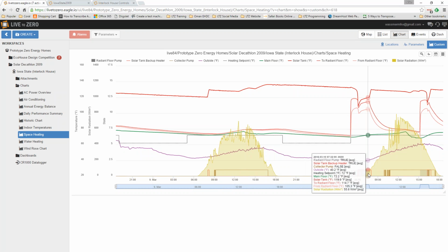So the backup heating element was on for about, I think it was, 2 hours, 6:06 through, okay, 2 hours. So 5 kilowatts continuous for 2 hours is how many kilowatt hours? Pop quiz. So kilowatt hours again is what you see on your electricity bill, right? So that's the magic number that we're tracking. So 5 kilowatts during a 2-hour period. How many kilowatt hours is that? 10. Yeah. All right. Well done.